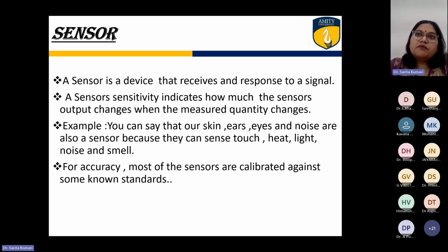Now, when we are talking about very high temperature, like above 2200 degrees centigrade, there we are using optical sensors, optical pyrometers to measure the temperature. So we can just imagine or see how the temperature sensors have varied applications. It is of different types. It uses different principles to operate. Also, it can measure the temperature which is ranging from minus 30-40 degrees centigrade up to 2500 degrees centigrade or beyond. So that is the beauty of this particular device, which is being used for measurement purpose.